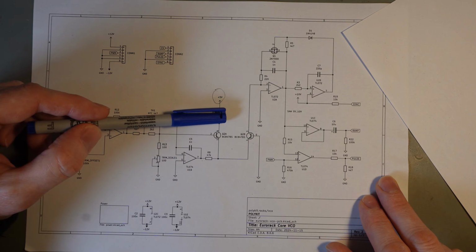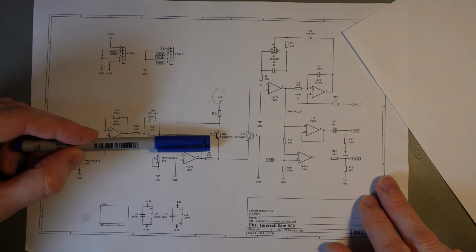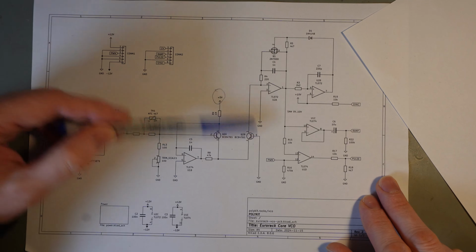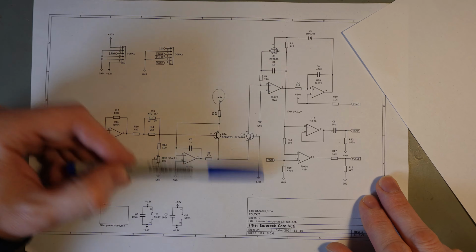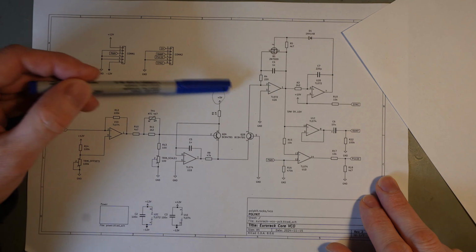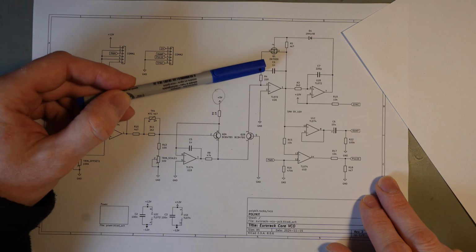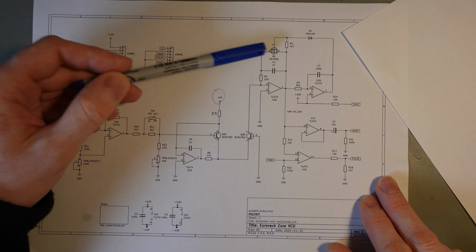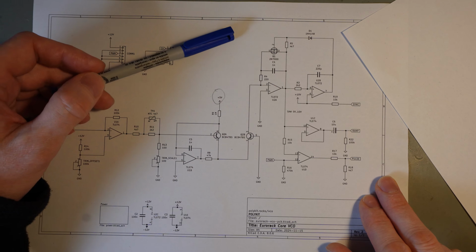This is basically a differential amplifier which has a voltage control, and with this you can control how much current you can get out of the oscillator core. And by changing the amount of charge that is going into the capacitor, you change the time, how fast it is charged, and subsequently the frequency here.